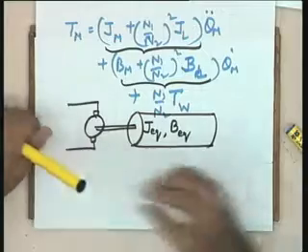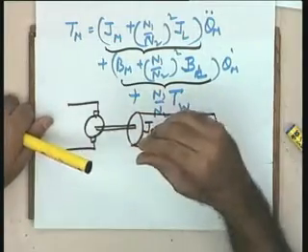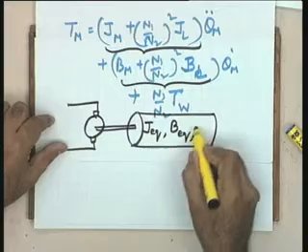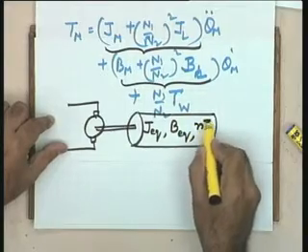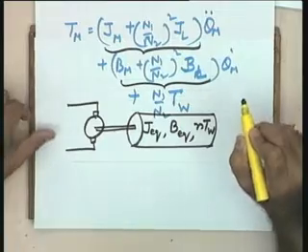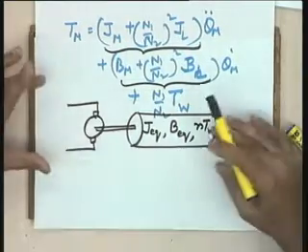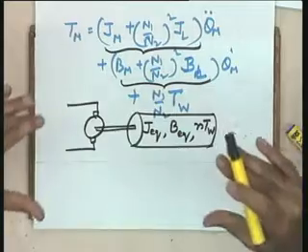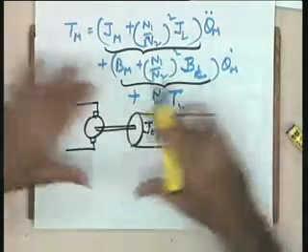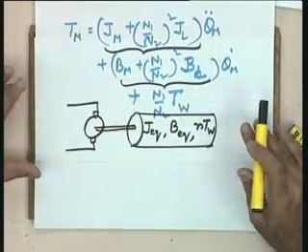And what is the disturbance directly coming on the motor shaft? Actually, physically speaking, the disturbance is coming on the load shaft, but if you take the disturbance as N into TW, where N is the gear ratio equal to N1 by N2, this becomes the representation. And why did we take this representation? Because writing the mathematical equation for this representation becomes simple.